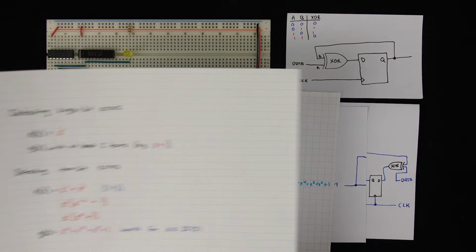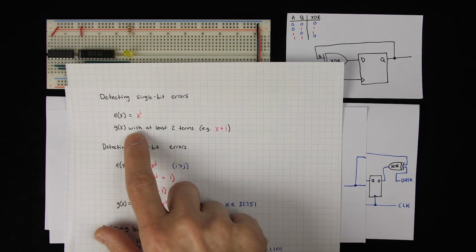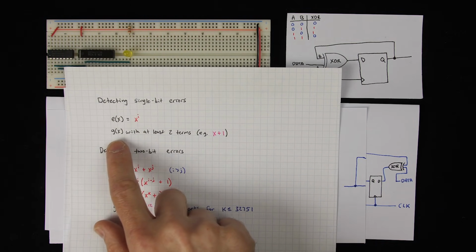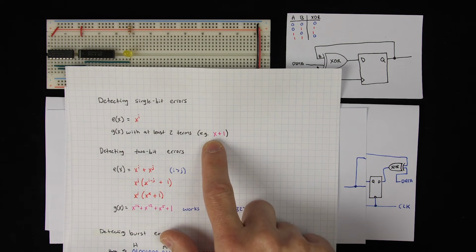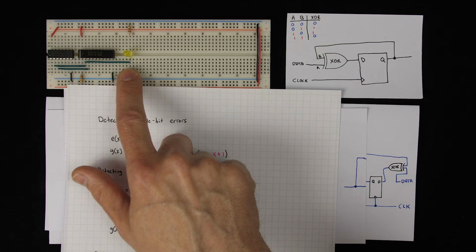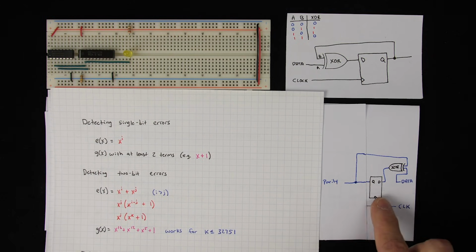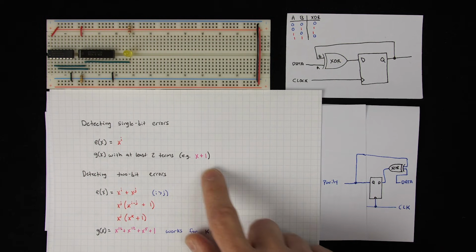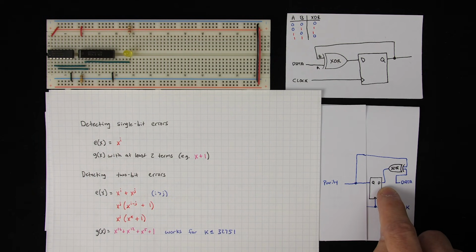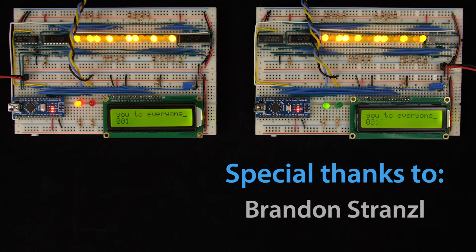And in fact, in the last video, when I talked about how you might go about choosing a polynomial, I mentioned that in order to detect a single bit error, you need a polynomial that has at least 2 terms. For example, x plus 1. Well, x plus 1 is a first degree polynomial. And so if that is your generator polynomial, you're going to get a 1-bit CRC. And in fact, a 1-bit CRC, if you build the circuit for it, is going to look like this. Because you're going to have your x term, which is the output of this, and then you're going to have your plus 1 term, which is the XOR gate that's going back into the input. So the fact that our parity circuit and our CRC circuit look so similar is no coincidence.